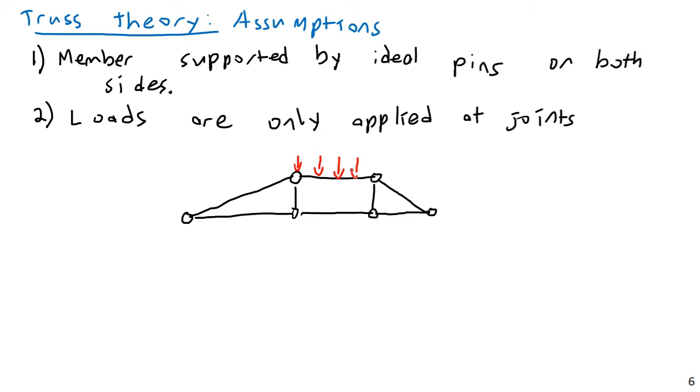And so what we have to worry about is self-weight, and the self-weight of members is not distributed at the joints. It's gathered at the joints, but it is generated throughout the entire length of the member. It's always going to be generated throughout the entire length of the member. So we know that this is completely impossible. I don't feel the need to draw all of these, but it does give the impression. So that means that in truss members, there is always going to be some moment.